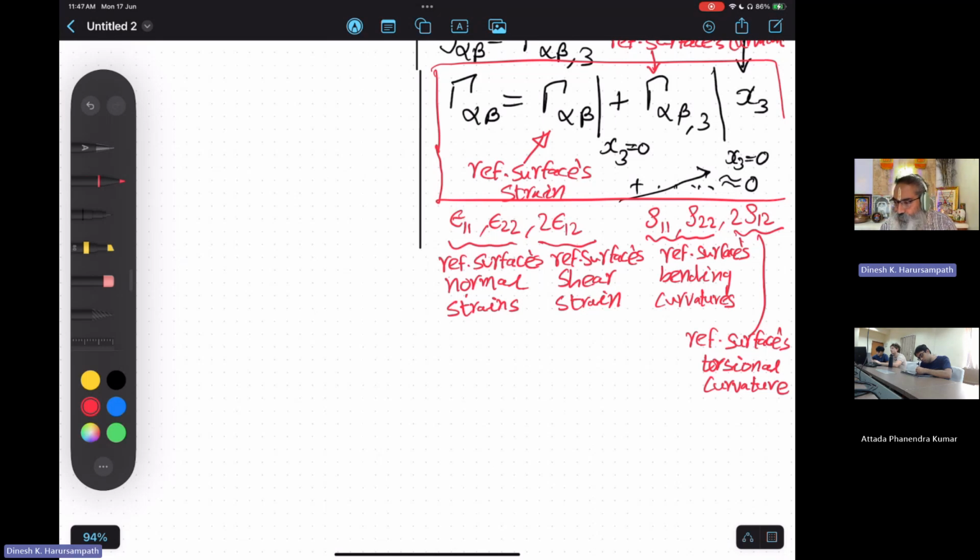So in other words, you're having something that you're trying to bend. So different layers will have different bending curvatures. If I'm trying to bend this upwards, if this is a part of an aircraft wing, we know that the lift distribution is such that this will anyway bend upwards. So if it's bending upwards, you see that the top layers have lesser curvature compared to the bottom layers. In other words, the radius of curvature is more for the bottom, but the curvature itself is lower for the bottom layers because the curvature is defined as 1 divided by the radius of curvature.